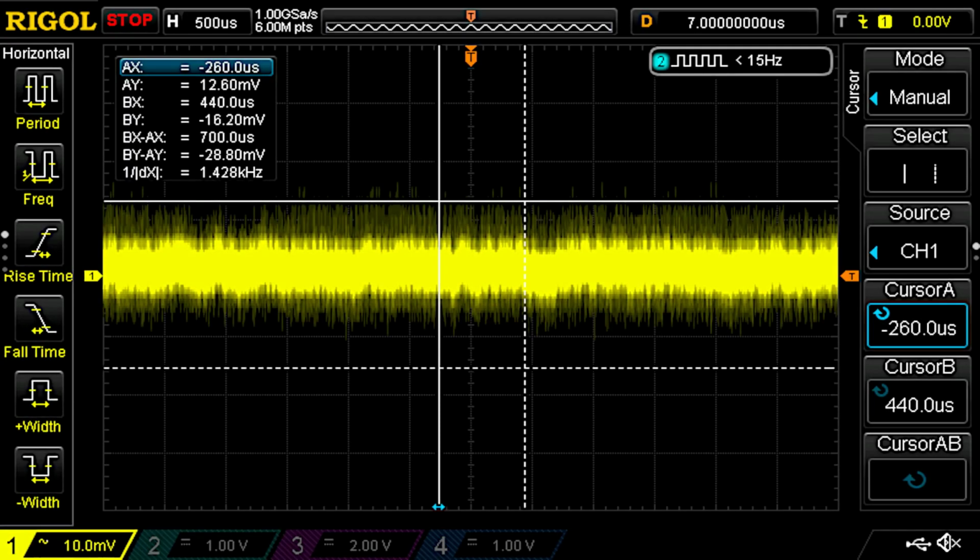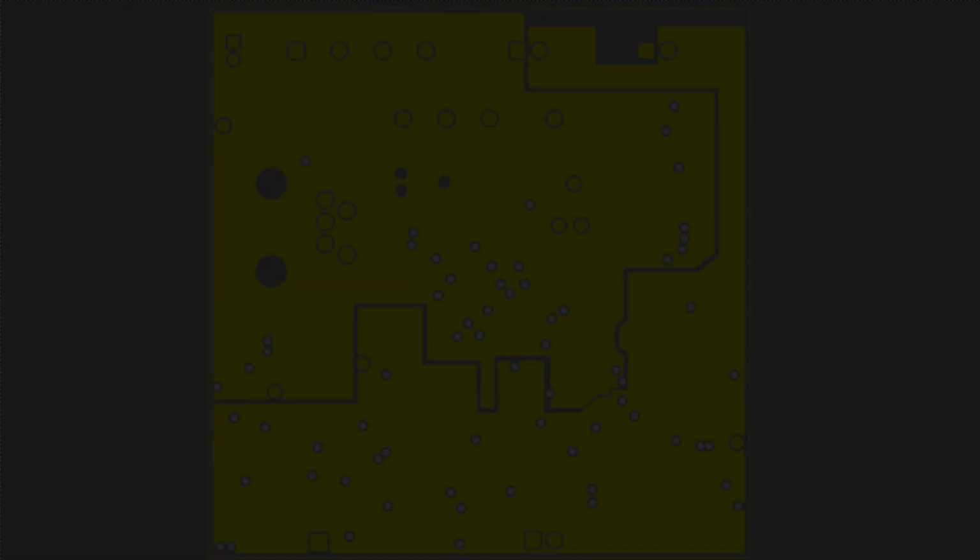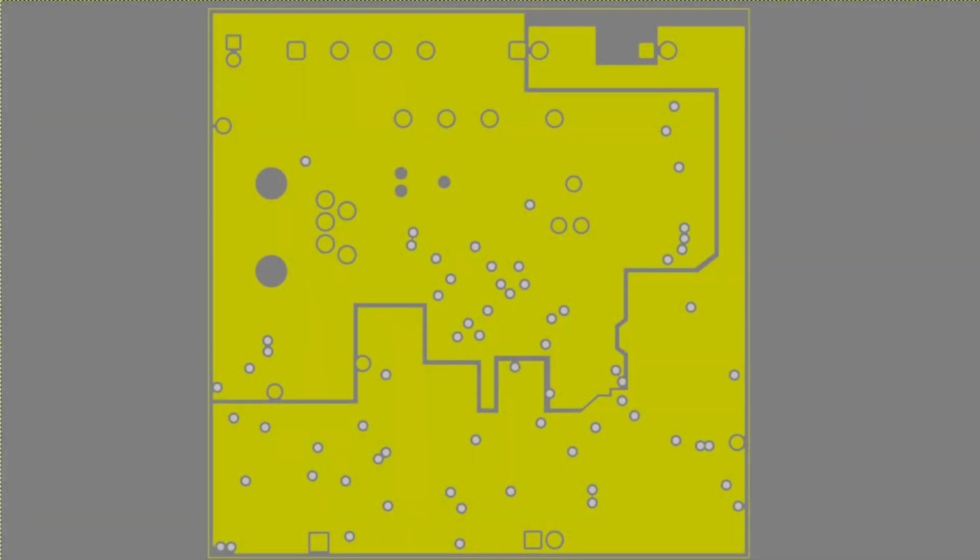Finally, this is what I get with the scope probe tip shorted to the end of the ground spring, touching ground on the PC board. So a lot of the noise I'm seeing on the voltage rails is not really there. And there is even a bit more complications.